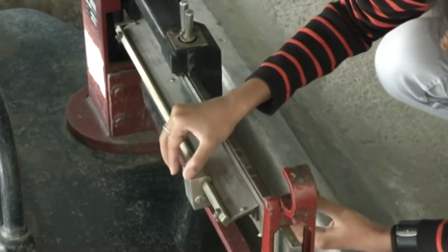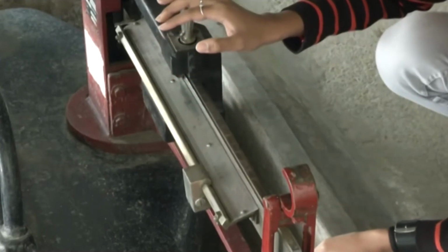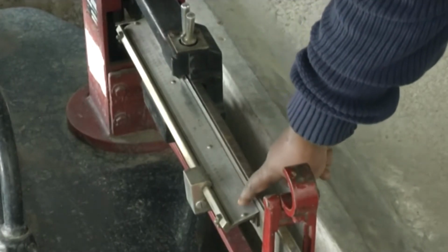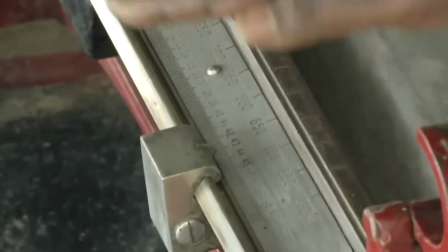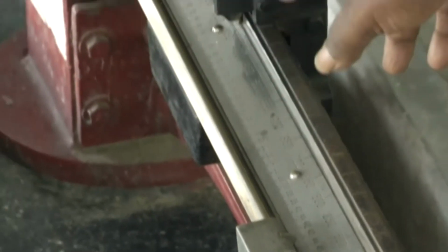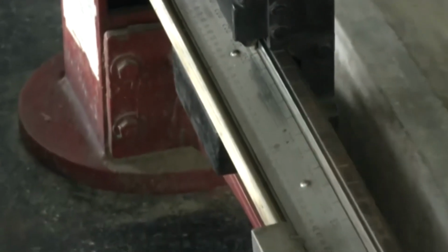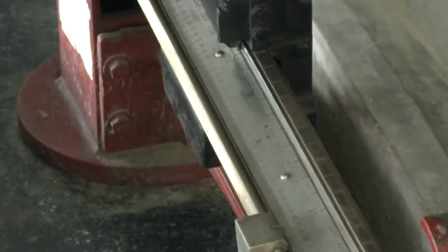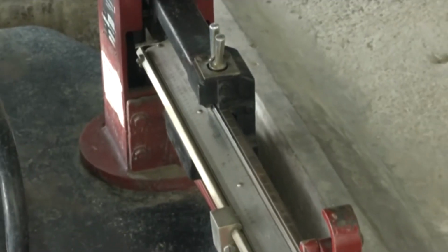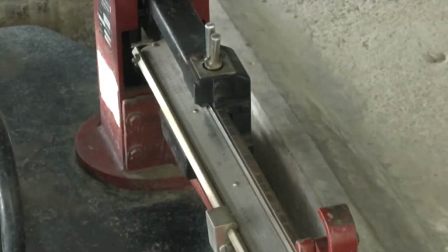Slightly you have to take it back. Yeah, it's okay. Thank you. Mind your head. What she has done, you could see this is a scale here, right? And you have to make this scale horizontal. So first you adjust from this lever, and for the final correction you do from the small weight here. Once this is done, it's like a vernier caliper. You read the main scale and the vernier scale, and you note down the weight.